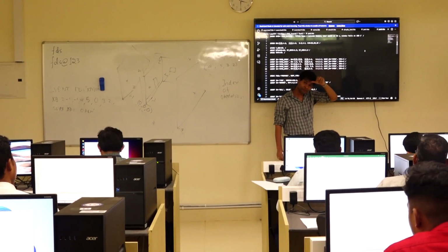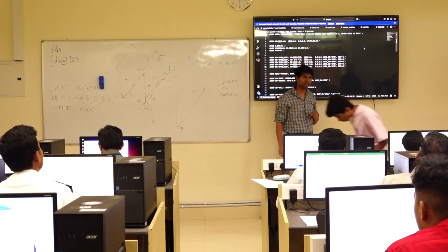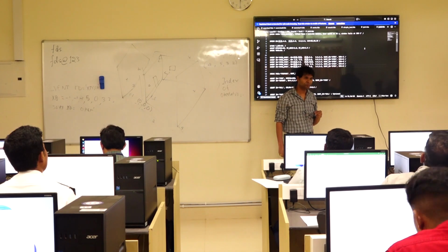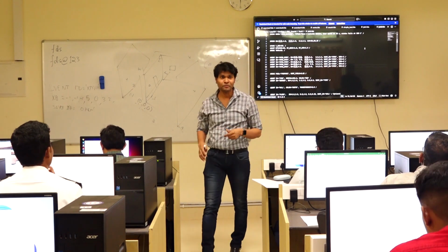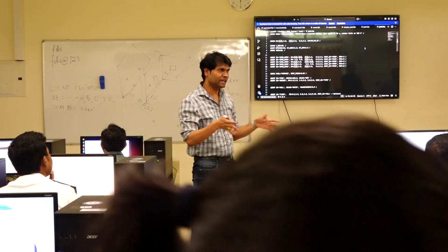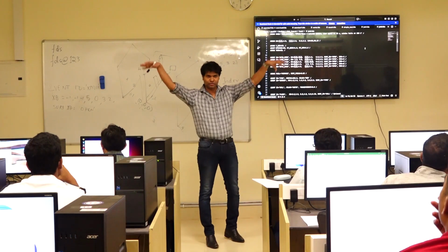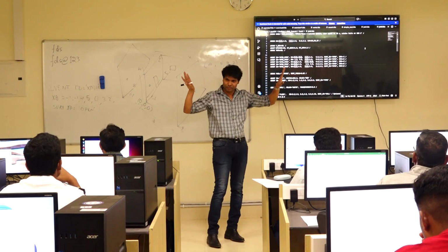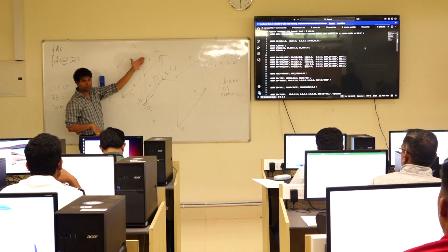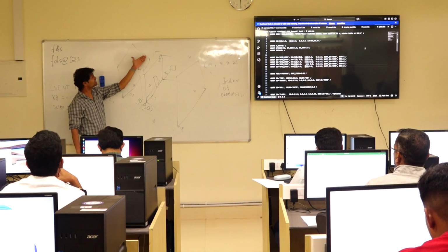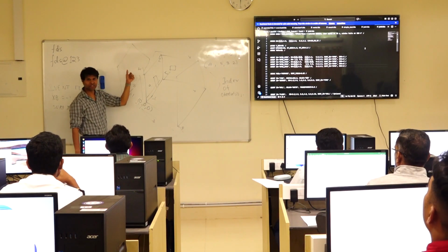Are you with me? Everybody understands why IOR is -1? Okay? No? Okay. So let's imagine this is a room. The combustion products are going to be formed, and they're going to flow into the atmosphere. So this is your x min plane. FDS needs to know which way the products are going to go into the atmosphere.